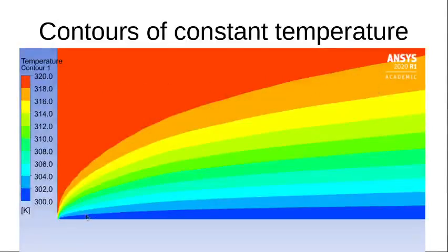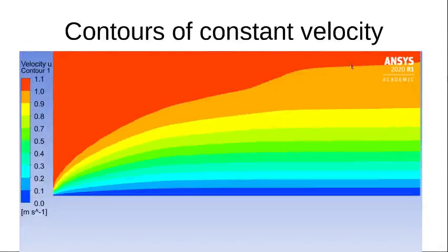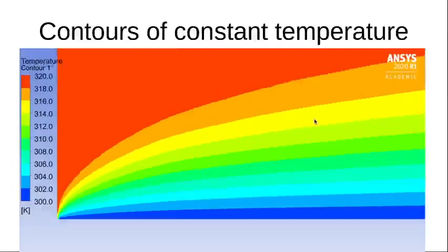Okay, so for the thickness of the boundary layer, again in this case the vertical direction is scaled up by a factor of 20. So if this looks like 5 centimeters, it is like 2.5 centimeters. So 30 centimeters is the length and 2.5 centimeters the height. I have just enlarged this so as to show you. The thickness of the boundary layer at the end of the plate goes to somewhere close to that. You can also see, comparing the previous slide and this slide, that the velocity and temperature boundary layers are not enormously different. The thickness of the boundary layer is quite similar in the two.